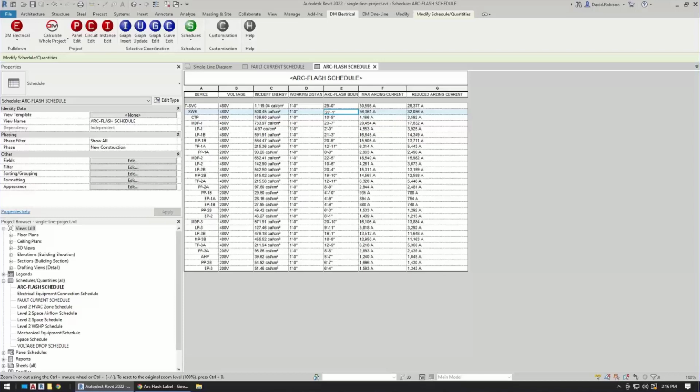This is a place where something like SKM or Easy Power actually does a better job than we do at this point. So if you're doing those calculations and you need the arc flash in utility mode and in generator mode, you have to jump through a little bit of hoops there. We calculate the fault in both, but then we always use the larger fault. But as we were seeing, the larger fault ends up being a larger arcing current, and the larger arcing current is not always the larger incident energy.